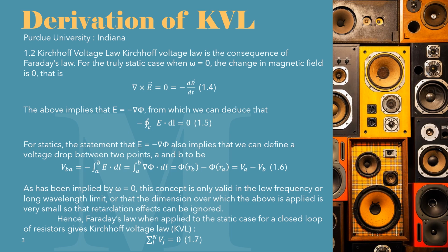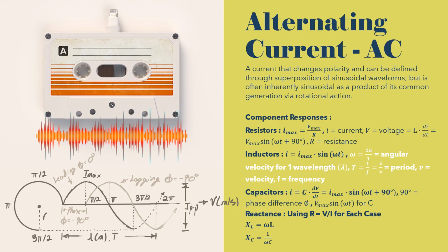However, there is a lower frequency limit as KVL assumes a constant magnetic field, so if the frequency is high enough that the field is constantly collapsing and cannot stabilize, meaning the current is constantly changing and the magnetic field as a result, or the current operates over a distance long enough that the change in polarity through the wires is distributed and propagates rather than being instantaneous, which additionally introduces other effects such as reflection, which must be considered, then KVL fails.